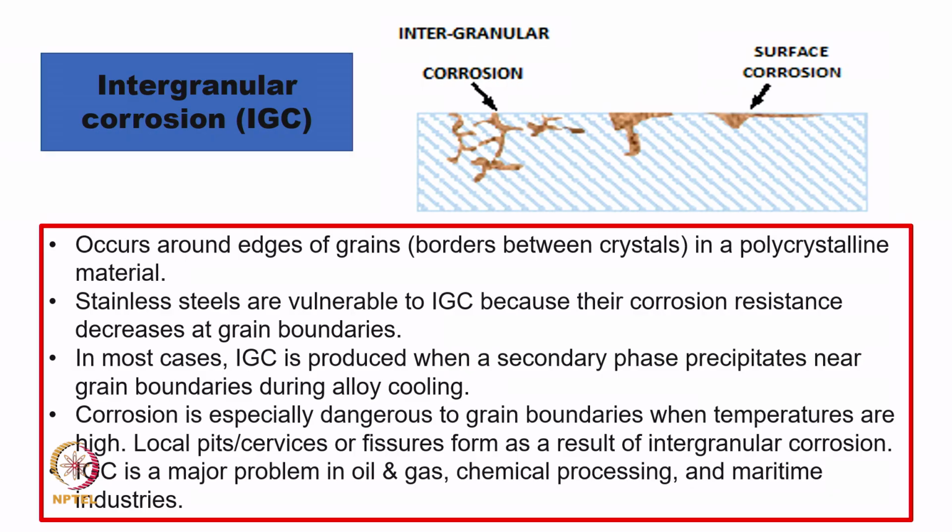So, this topic is very interesting from this angle, to understand corrosion, and to understand that we cannot simply say that this material is corrosion resistant. Quite possibly we need to mention the temperature, and we need to mention the environment also. All three together will tell whether the material will be able to sustain corrosion, or will be acting as corrosion resistant or not. Now, we will try to understand a few more phenomena.